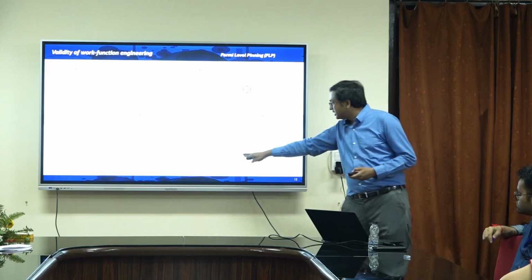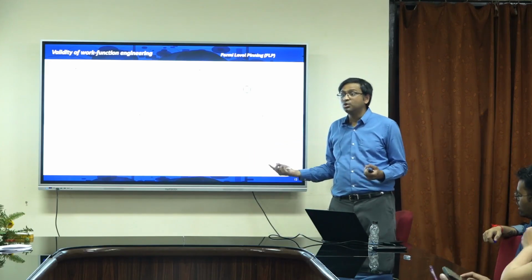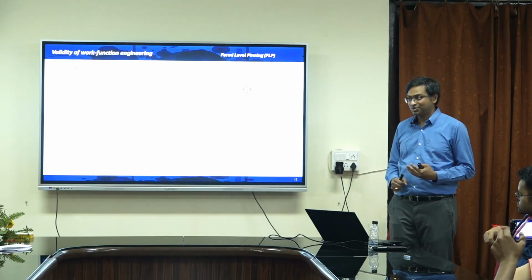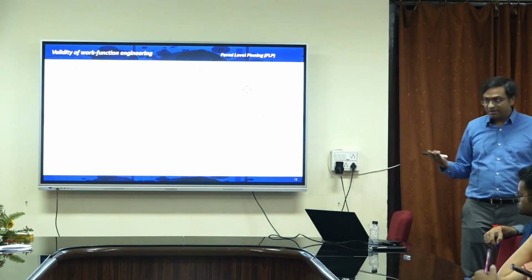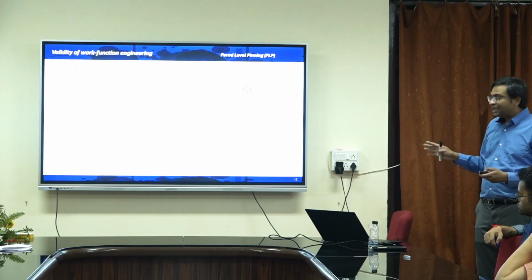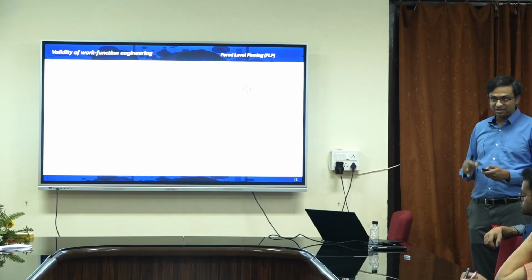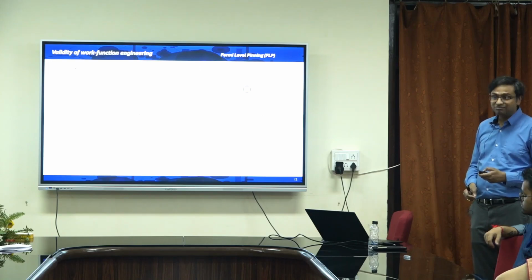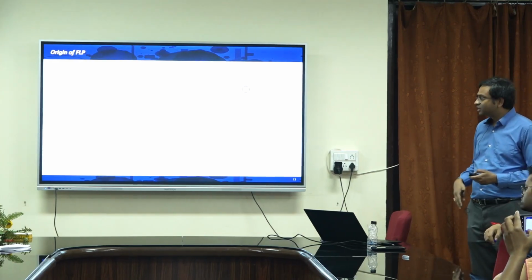If only a part of the work function goes in here, and if this factor is 0.1, now I am looking for a material with a work function of 10 eV to get a negative Schottky barrier height, right? If the factor is less than 1, I do not get the full benefit of my metal work function, right? And this is something that we see. Alpha equals 1 is the ideal case, but in experiments it is never ideal. For silicon, this number is 0.27, okay, and for MoS2 it is even worse, it is 0.1, okay. And this happens because of something called metal induced gap states.